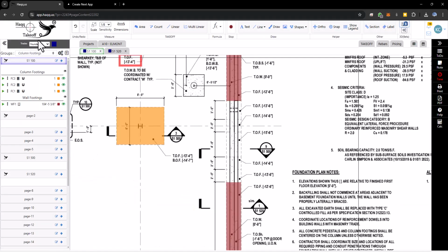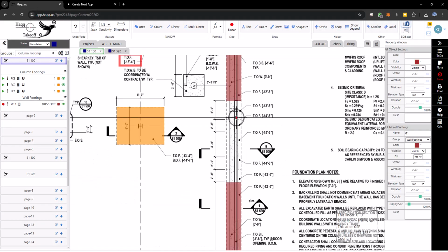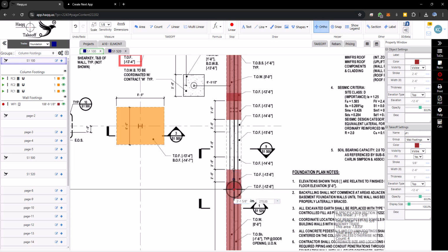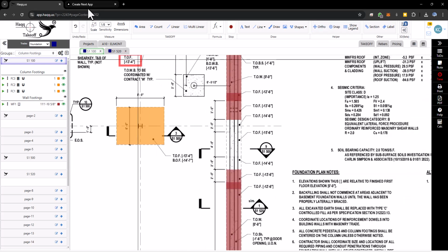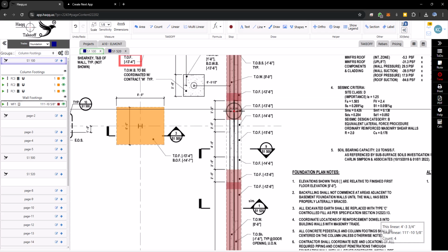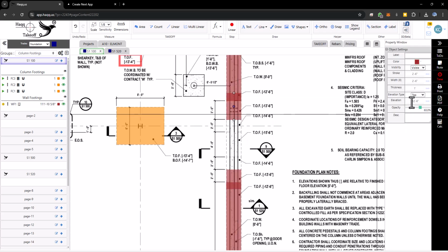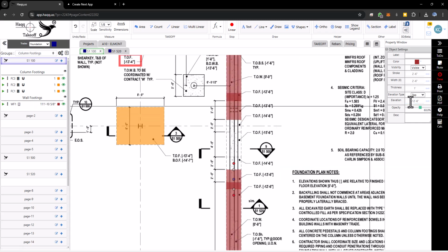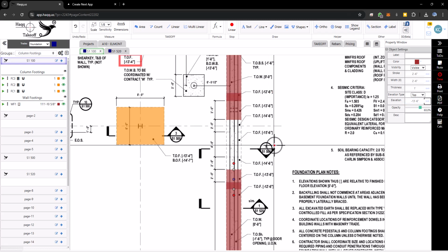Now let's add the stepped footings by pressing the Play button next to WF1 from the left panel. We'll start from the first step, extending under the higher footing by a couple of feet. Since we're using the same footing element, WF1, the 3D model will initially display them at the same elevation. Switch to 2D, select Edit for the stepped footing we just added, go to the right panel, and change the top of footing elevation to -13 feet 6 inches.